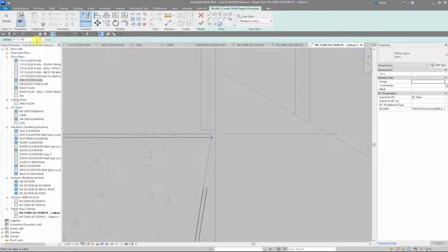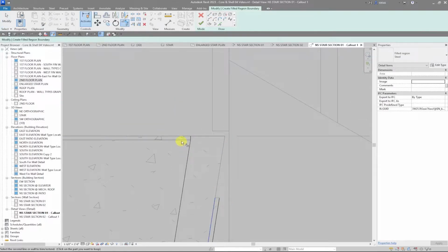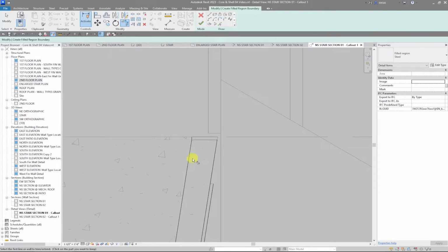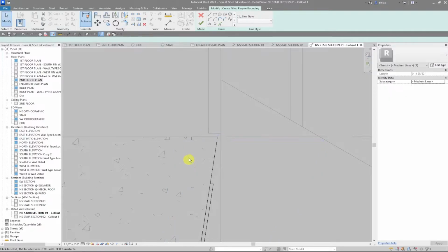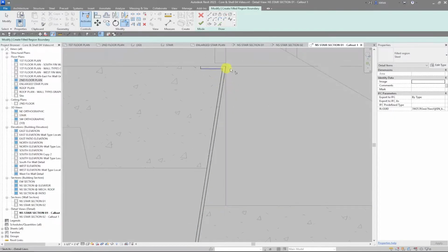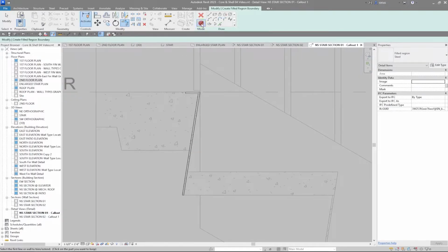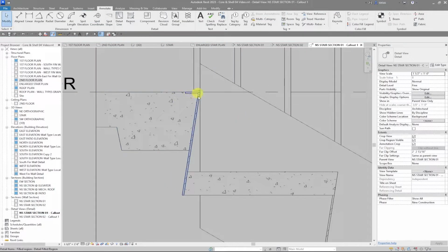And then let's do a 1-inch offset from the back side here. That just gets me, well, that kind of screwed me up. It trimmed that one back. So now I can trim this, see that line to there, then this line to there, and that line to there. I can get rid of my 1-inch offset because that was basically just a layout line. And now I can trim this line to here. So I kind of have this 7 shape for my riser, and I can hit the green check mark, and now I have a steel riser.